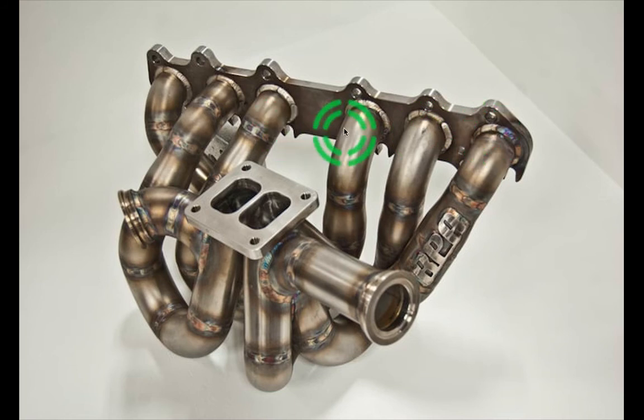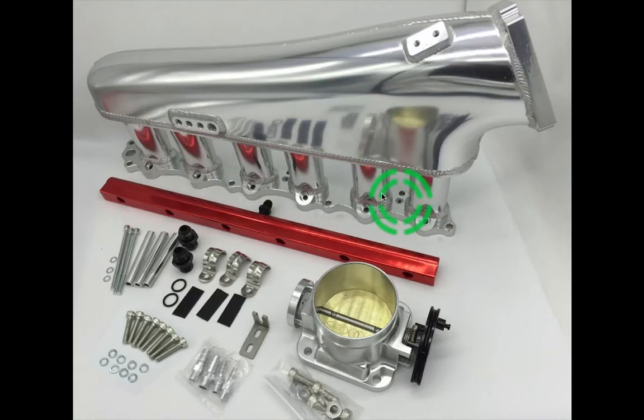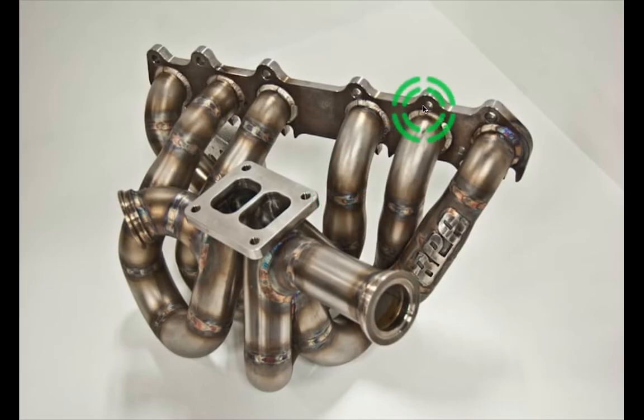Similarly, the intake tank turbulence, which I was talking about, is again the same thing. At higher RPM, all that does not make any difference. At higher RPM, the pressure starts channeling itself in such a way that it starts flowing how it should flow, right? So at higher RPM, actually, this has now become a restriction.